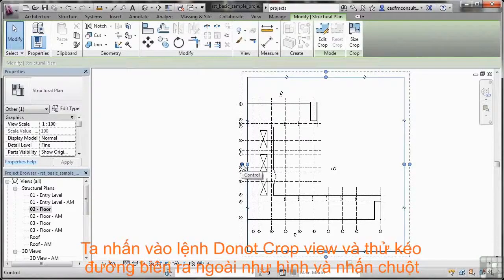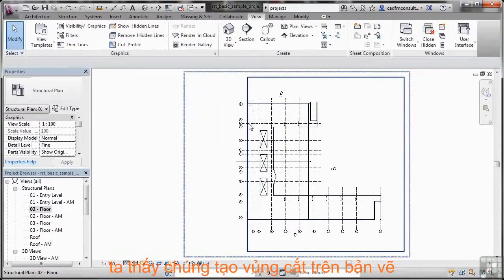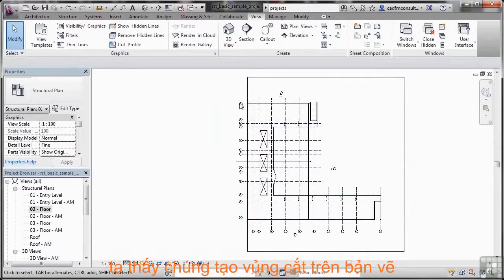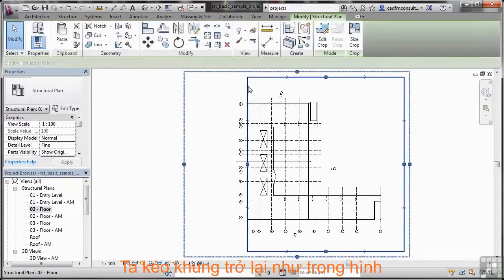And also if I drag this one, this is my control. If I come out here to here like this and click like that, what it does is it actually crops the view. Any annotation goes out to that point there. So I've got those two different settings. That's the actual view, and the dotted one is the annotation, how far the annotation will show.